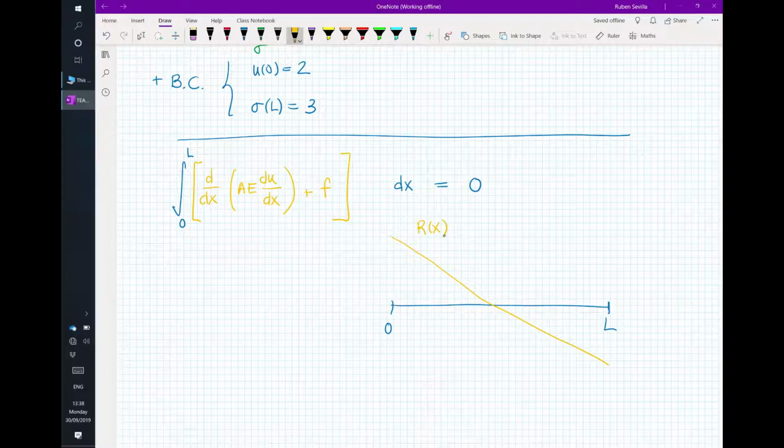The residual must be zero, because residual zero means equilibrium of forces. Are you happy with something like that? It satisfies that the integral is zero, correct? Because this area could cancel this one in here. But if I go to this particular point, my residual is really big, meaning that I'm not satisfying equilibrium very well at that point. So that solution looks not very good.